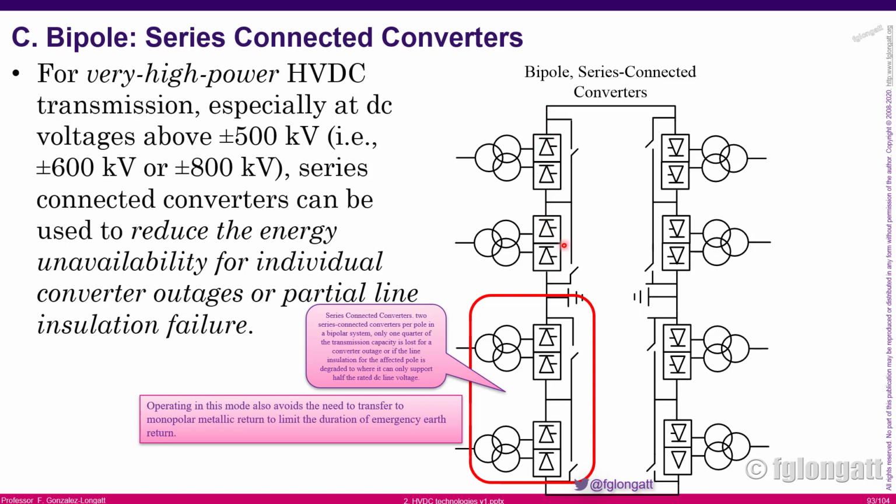If you can imagine one of those devices using 300 kV, plus 300 kV, we are reaching here 600 kV, okay? And what is the idea of those switches here? Those switches, which are located in a shunt connection to the converters, are basically for when this converter goes out of operation: we can disconnect this converter and this converter, and we can close those switches and keep using the other cable, okay? The idea is that the cables can still be in use inside the configuration, okay?